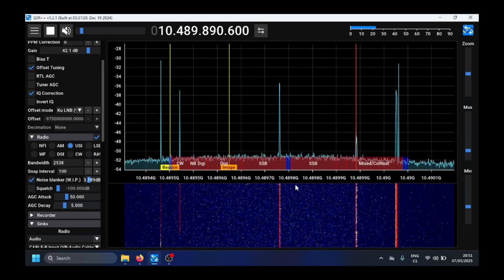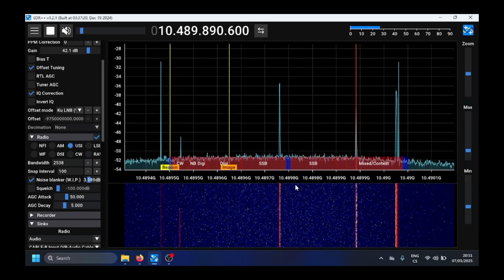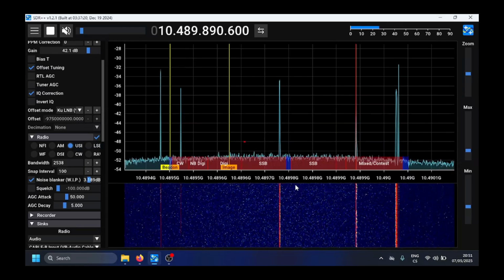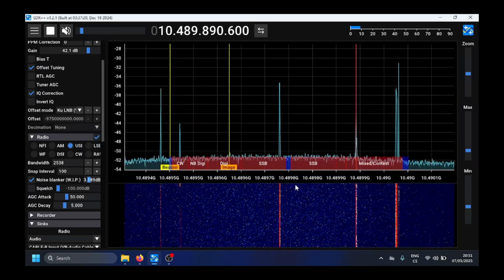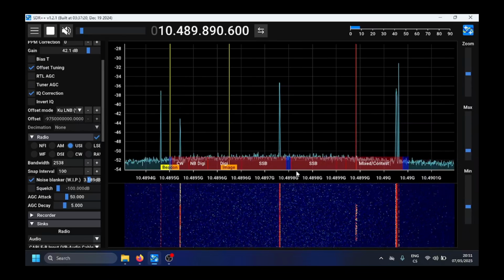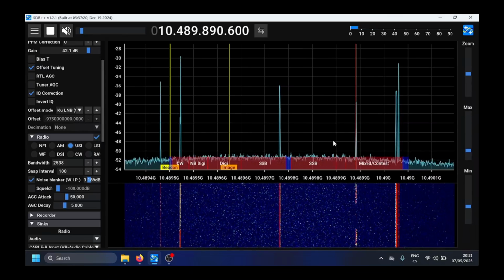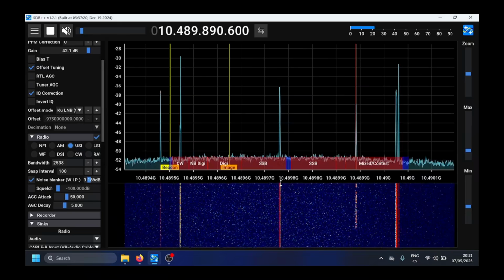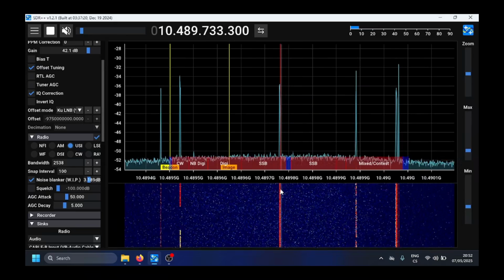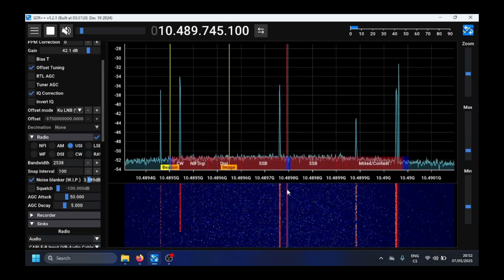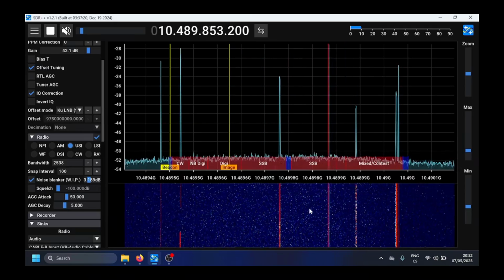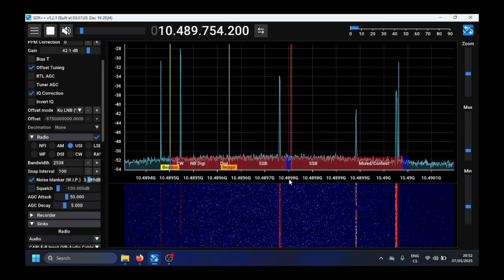Currently, the conditions are pretty much perfect for this LNB to do the best it possibly can, because the sun just now set, which means there's no direct heating on the LNB. There's absolutely no wind whatsoever, so there are no rapid temperature changes on the LNB. Anyway, my point is that the frequency does drift, and currently it is drifted like 20 kilohertz down. It's possible that as the LNB heats up throughout the day, the frequency is going to go another 40 kilohertz up, and it's kind of going to oscillate around 9.75 gigahertz, right? It's not going to be perfectly stable.